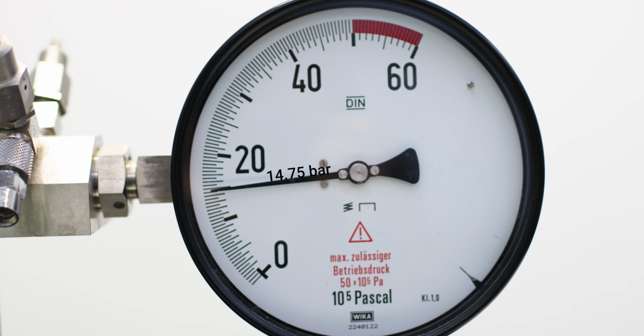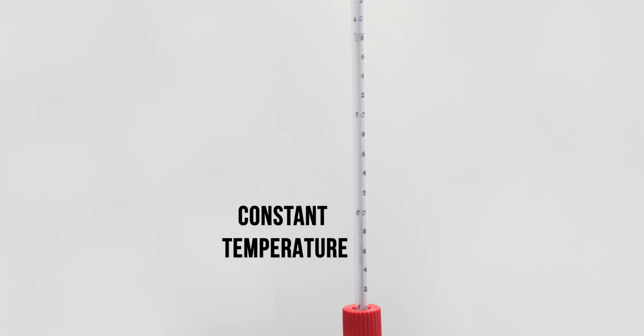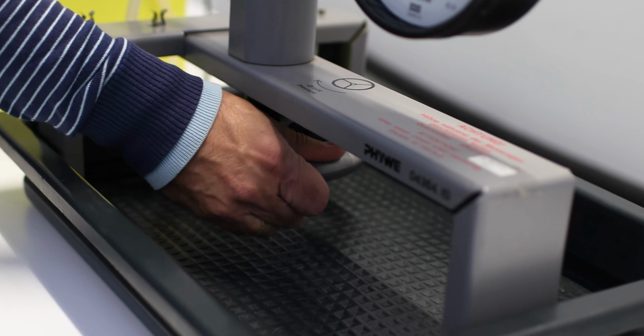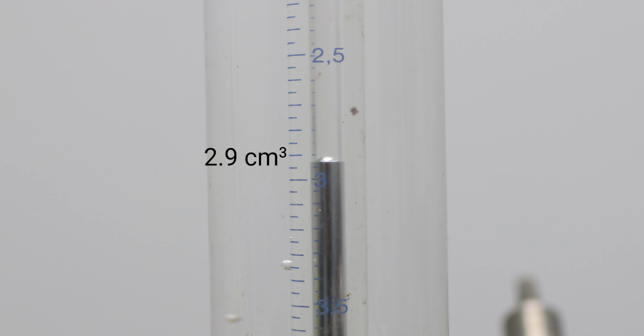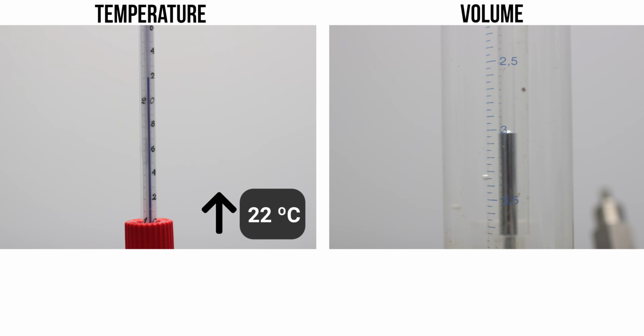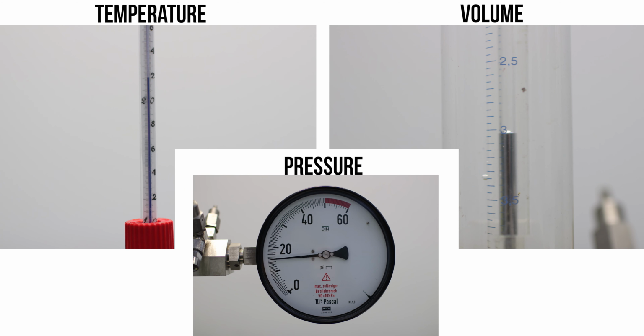This value corresponds to the behavior of the fluid when we have chosen given values of temperature and volume. Keeping a constant temperature value, we turn the wheel in order to obtain a new volume value, for example, 2.9 cubic centimeters. Looking at the manometer, we can see that pressure has been modified to 15.0 bar as a result of the fluid behavior. If the temperature value is modified to 22 degrees Celsius and the same value of 3 cubic centimeters is selected, as in the previous experience, a new pressure value is reached, corresponding to 15.0 bar, different than the one of the first experience.